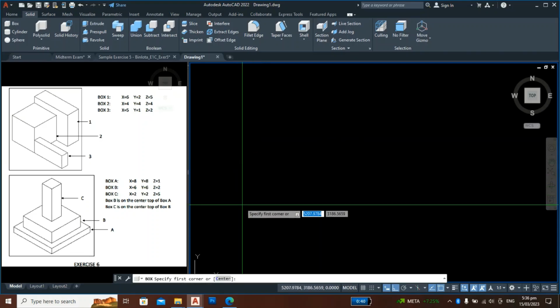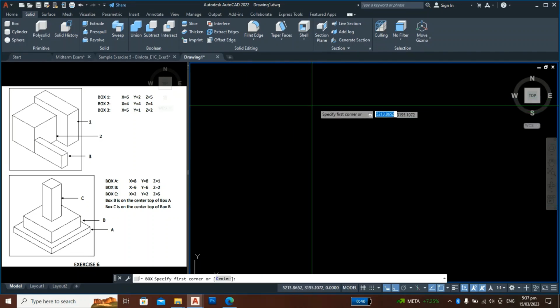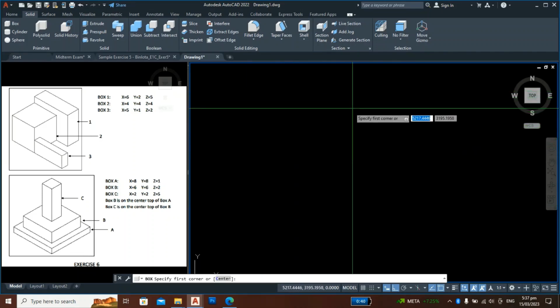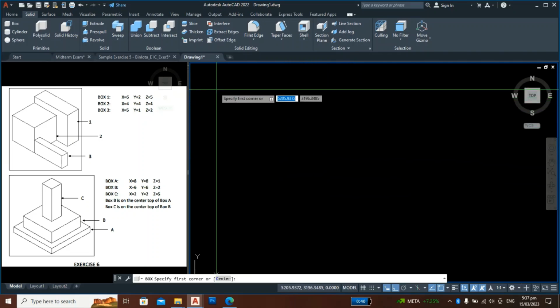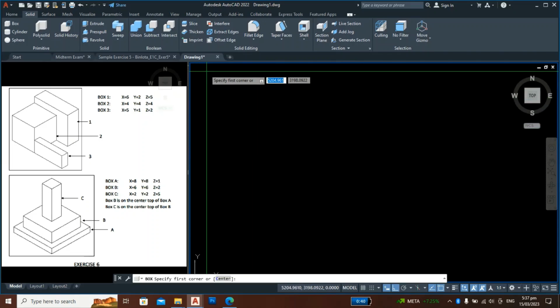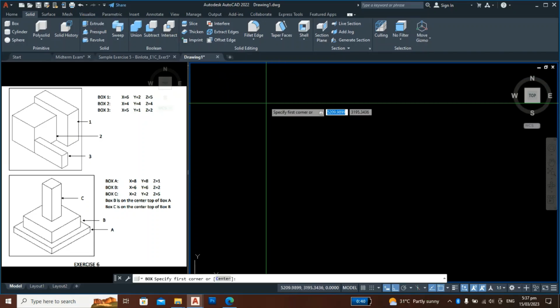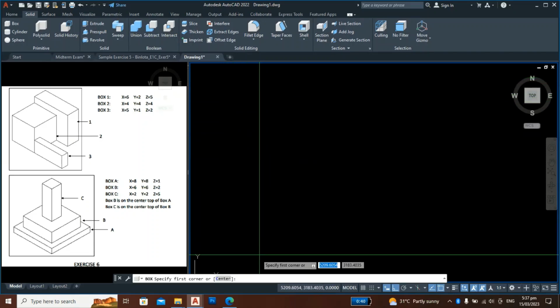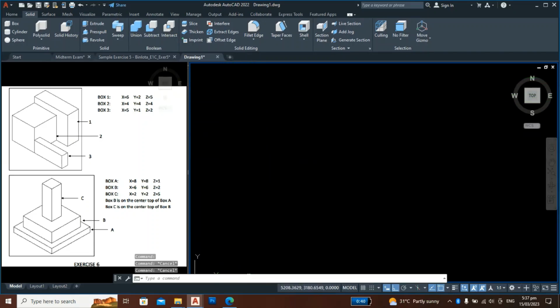But before that, okay, let's make the visual style here shaded, so that we can see the visual styles options here later, even if we will not click the visualize tab, for example. But since there's still none, you can type shade first. Okay, so I escape this, cancel the command first. You can type shade here, or you can click this visualize.